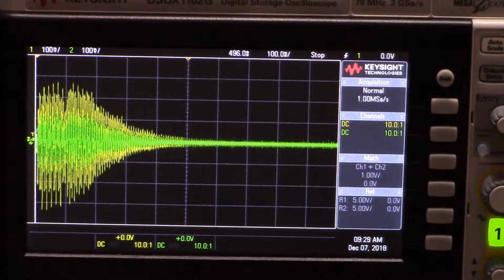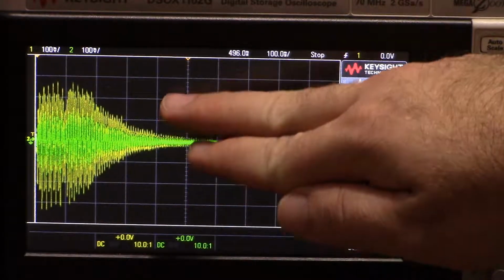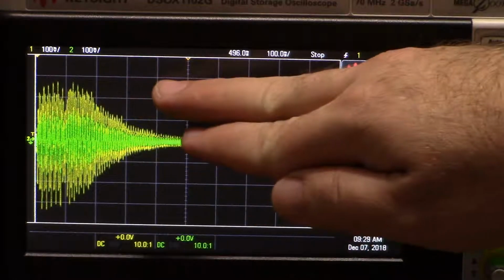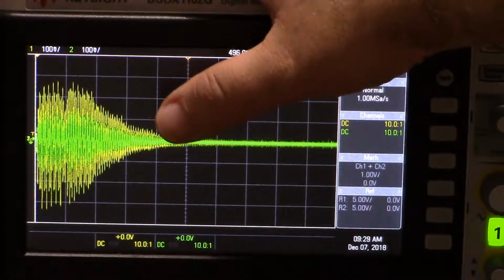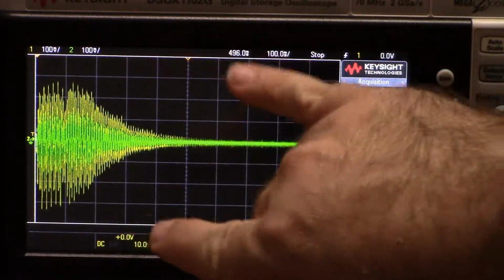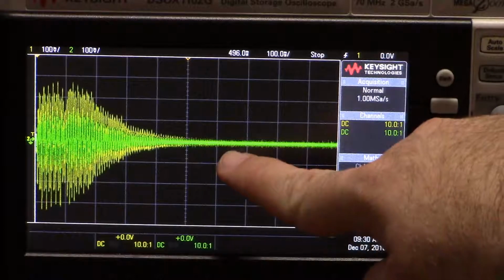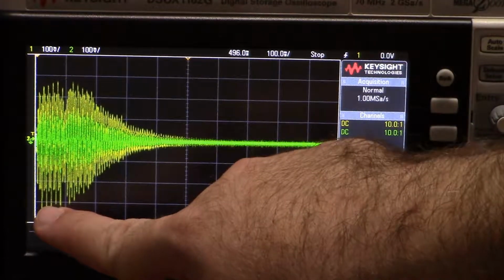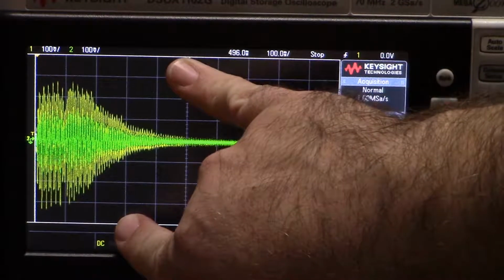So we seem to have consistency now. All of them seem to be about the same height. So 250 millivolts to 300 millivolts. So I'm going to say for this device, the expected signal range at maximum output volume is, oh, and if we look lower here, 10, 20, 30, and it's a little bit past, so maybe we want to say 400, so 800 peak to peak.